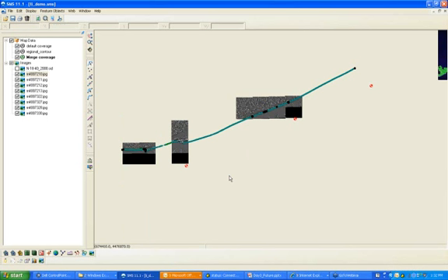All right, so we have our three wave gauge locations. Now I want to go ahead and set up the grid frame. So again, in this case, the grid frame is going to start here. If we walk along it from here to here, the shoreline will always be on your left.